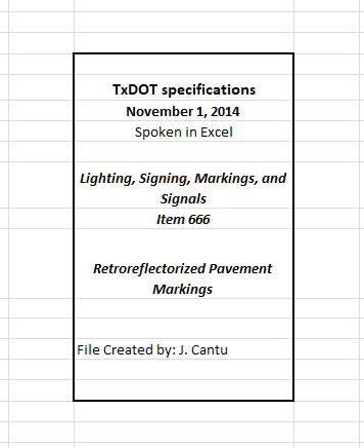4.6 Performance Period. All markings must meet the requirements of this specification for at least 30 calendar days after installation. Unless otherwise directed, remove pavement markings that fail to meet requirements, and replace at the contractor's expense. Replace failing markings within 30 days of notification. All replacement markings must also meet all requirements of this item for a minimum of 30 calendar days after installation.